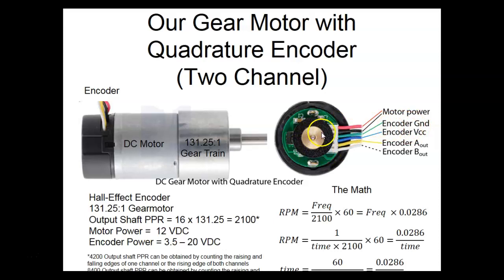This is the actual encoder, guys, and it's using a Hall effect. The way this thing is set up, a rotary magnet like this, we should actually divide it like this, and this would be north, south, north, south, north, south. What we actually end up with is 16 pulses out of our magnet per revolution. But we're not concerned with that when we're measuring the speed. We don't want to know the speed of this. We want to know what's going on out here.